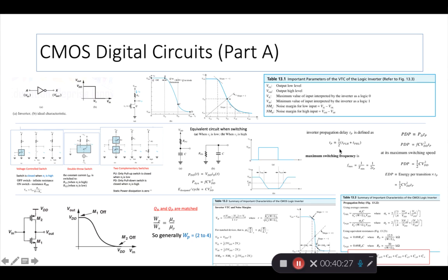Okay. Next we come to actually putting the two transistors in one circuit, right? The NMOS at the bottom, which is shown here as M1, and the PMOS on the top. Sometimes this is shown as QN and QP in our book, but either way, the two transistors together, generally fabricated on one silicon crystal, it's called a CMOS device, right? It's two devices in one. So when you have this connection, we get the perfect possible inverter, right?